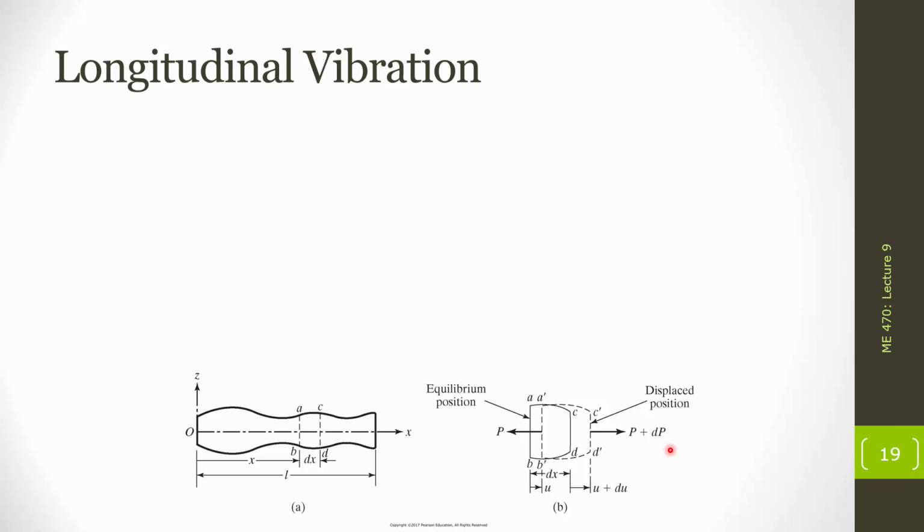So we'll get to looking at the sum of forces acting on this system, but we're already going to impose some limitations on the types of longitudinal vibration that we'll be looking at here. So first, we are only going to look at systems that are undergoing linear elastic deformation. So we're sticking in that linear elastic region. We are below the yield strength of our material, when we're in tension or in compression, and furthermore, when we're in compression, we are making sure that we are not buckling our column.